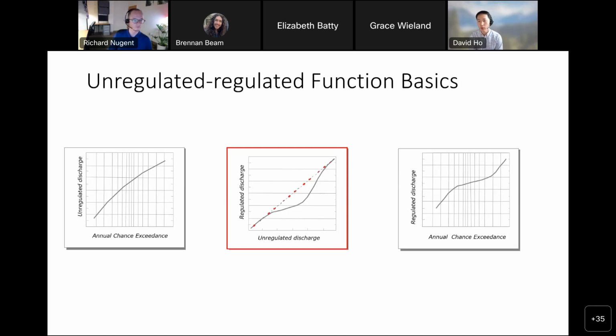We just talked about one way of creating a regulated curve, which is just to do a graphical flow frequency curve, which again is just drawing the curve. But then we had brought up some limitations about that, right? Namely that it's not repeatable, doesn't necessarily reflect uncertainty that well, and has challenges with extrapolating and incorporating historic information.